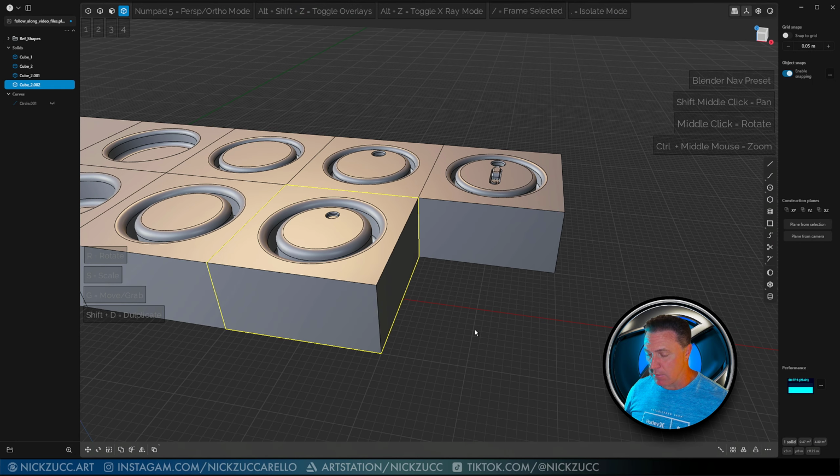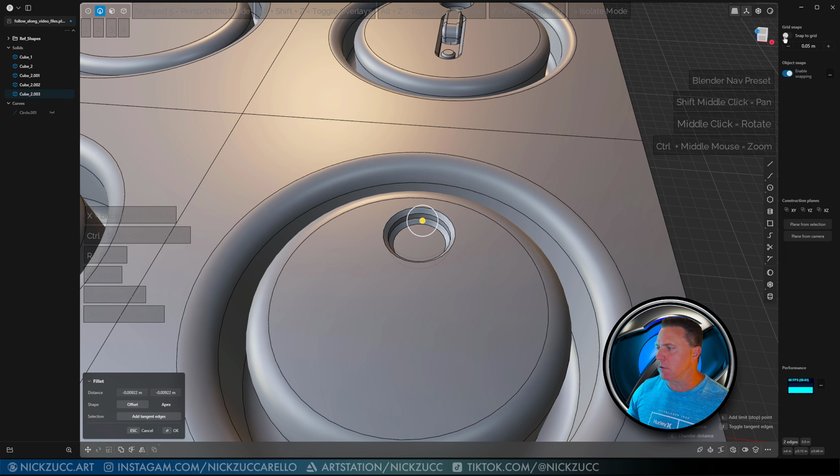I'm going to tap 2 and I'm going to select this edge here. I'm going to hold down Shift and I'm going to select both of these edges and then I'm going to do the chamfer. It's going to fail because I've got the grid snapping turned on and that's just too big of a distance for things. So let's try to get that within through here, something like that. And then maybe the snapping is affecting this as well. Again, I'm just trying to get a really small value within here. And so maybe you got to turn these things off to get this exactly where you want it to be.